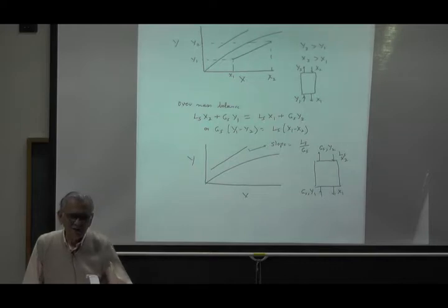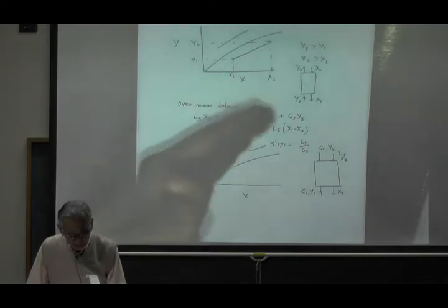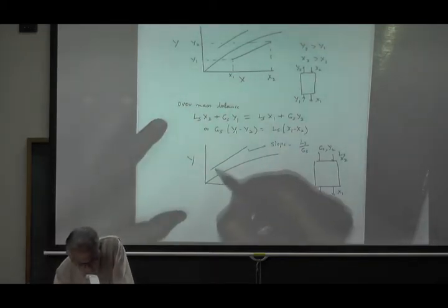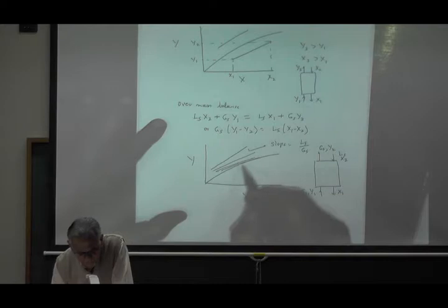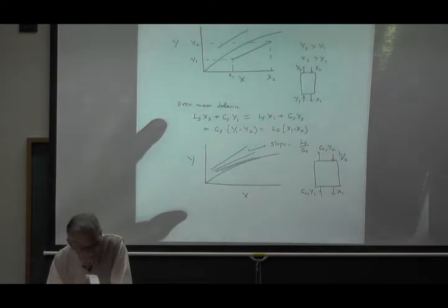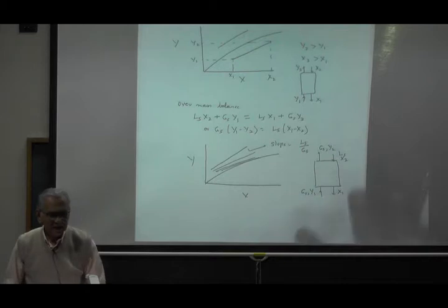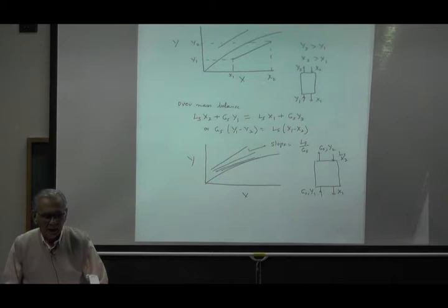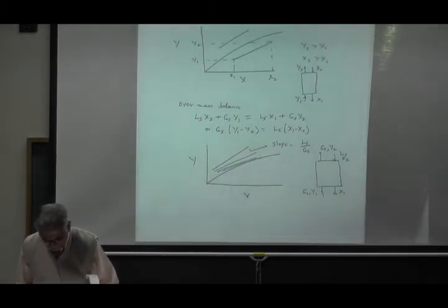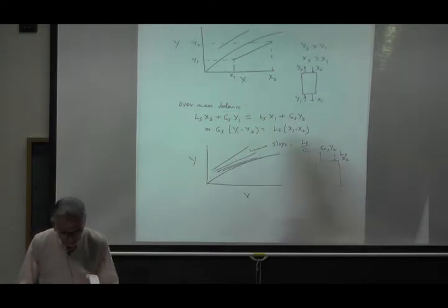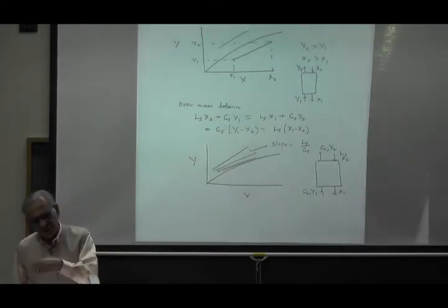Yeah, supposing you decrease the flow rate, and it will go on decreasing. So as you change the slope, this will decrease, and at some point it will either become tangent to this or start crossing this. Beyond that, so that is the minimum flow rate you can use to achieve that separation. We will do that in a little more detail after we have done some more of this, but I just wanted to mention it here that as you change the flow rate of the liquid, the slope will change.